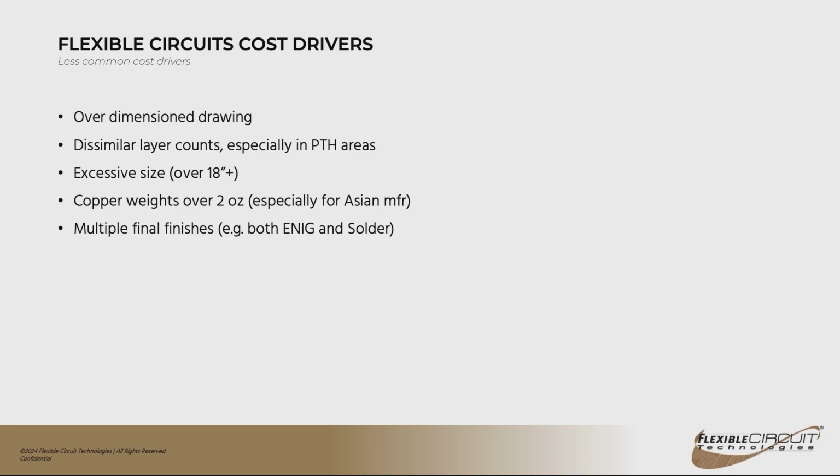We end up having to pre-make our materials because we don't stock any pre-clad polyester laminates, and the cost for us to do that operation is more than if we just bought a pre-clad polyimide substrate, which is going to give you better performance. So we definitely recommend going with polyimide over polyester.